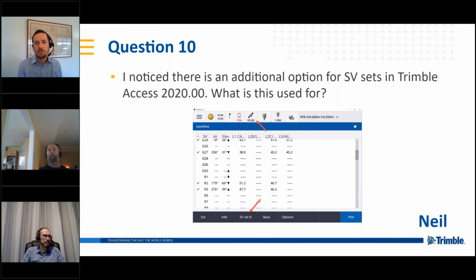So this menu, or this option to change from subset A to subset B and back to all, can be done from this screen, or choosing subset A and subset B can be chosen from the Measure RTK initialization menu, which is probably not used that much. But people doing this kind of work in the past may have done some independent measurement by doing a new initialization, and that Measure RTK initialization would reset the initialization. So it's a handy new feature.